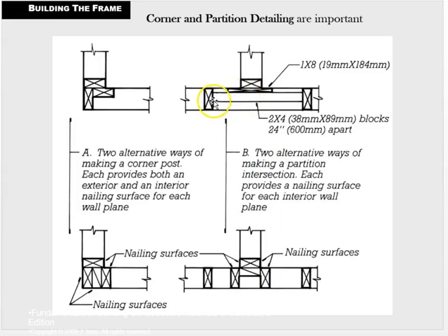Over here, rather than putting these 2 studs right up on this wall, we rely on the studs that are in place. So less wood, so that's a positive thing. And then we have blocking running from existing stud to existing stud. And then I guess it's kind of packed out here for some reason. I'm not sure why the blocking just wouldn't be up against this. But we could insulate it, and this piece. This piece is continuous. That's why that would be there. So this provides us, so it's a 1x8, providing us continuous nailing surface in this direction.